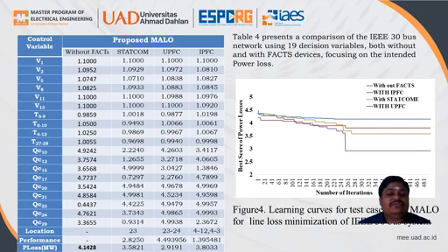Similarly, the UPFC is connected between buses 23 and 24, and the power loss is 2.9191 megawatts. In case of the IPFC, connected in between the two lines 4-12 and 4-13, the power loss minimization is 3.8033 megawatts. So in this table, the UPFC gives a better result compared to the STATCOM and the IPFC.